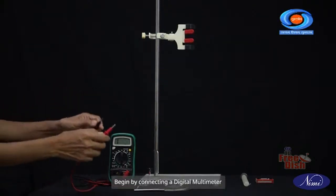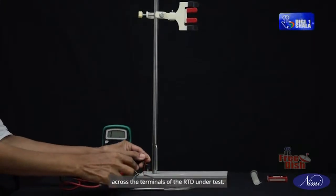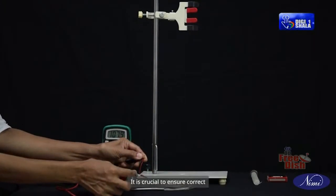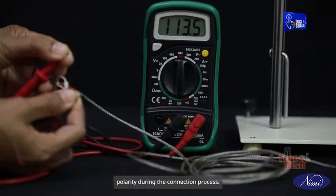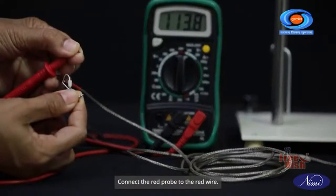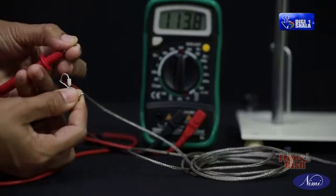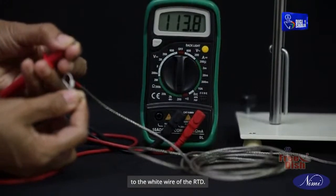Begin by connecting a digital multimeter across the terminals of the RTD under test. It is crucial to ensure correct polarity during the connection process. Connect the red probe to the red wire. Then, connect the black probe of the digital multimeter to the white wire of the RTD.